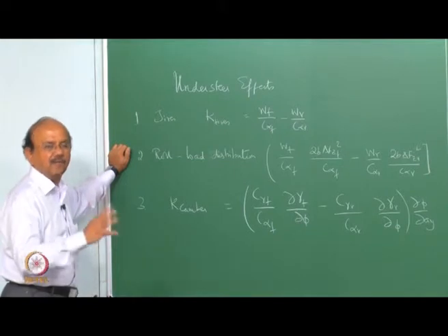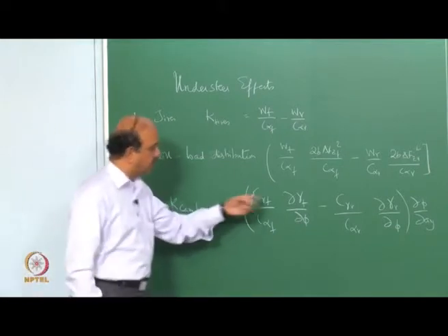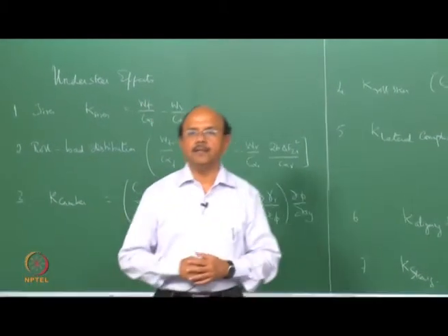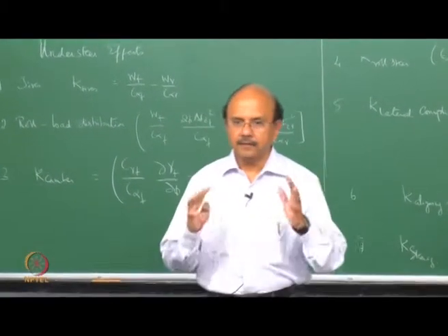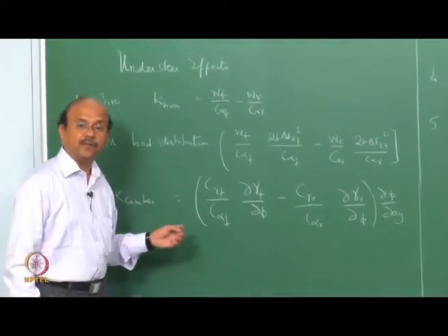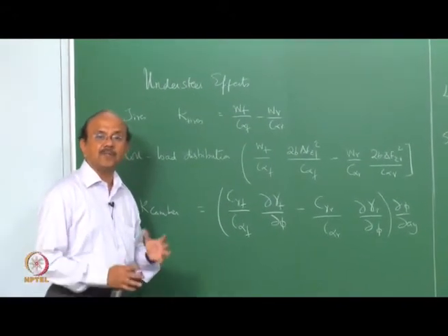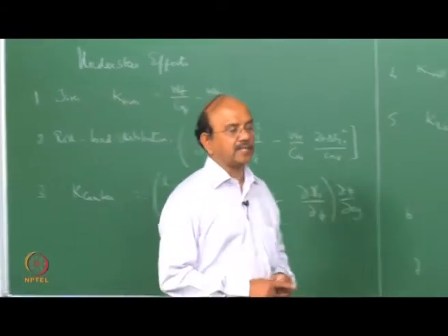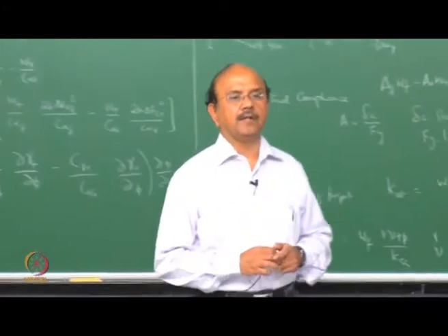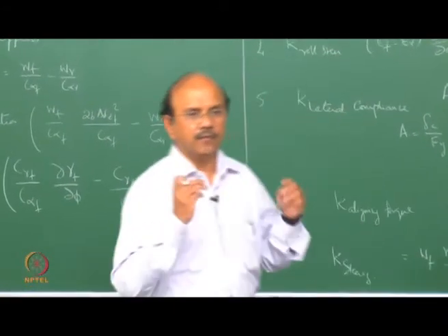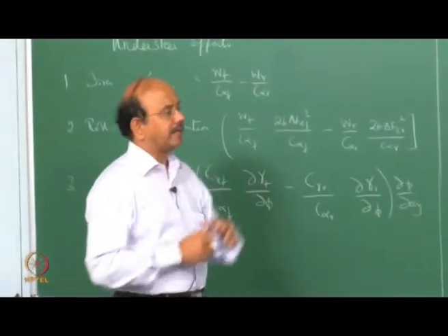That's the slope of this curve between the force and the camber. We saw that this also has an effect. I am very interested to find out what the camber change is due to the suspension mechanism, and that's what we are going to do as a big exercise in the next course on vehicle dynamics laboratory when we use packages like Adams.